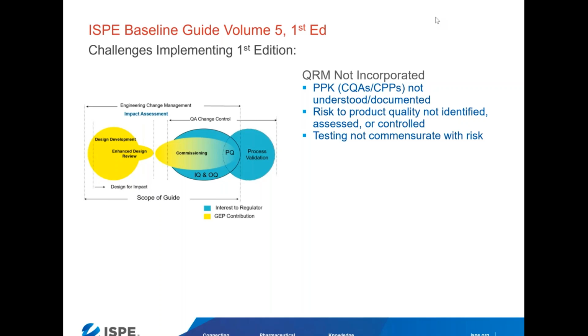If you're familiar with the system level impact assessment and component criticality assessment, this part of this process, it was really a bottom-up approach to risk assessment, looking primarily at the equipment systems rather than at the quality attributes of the product. And the outcome was very binary. You'd have yes and no questions that led to an is or is not decision. System would be direct, indirect, or no impact. A component would be critical or not critical, which is very binary.